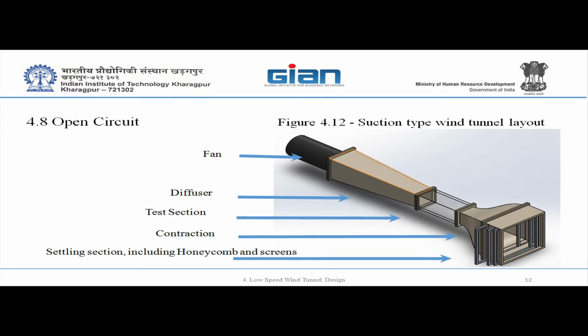To settle the turbulences, there should be some space. The settling of air is being done in the settling chamber by the elements that we are inserting there. You see the drawers we put there, starting with a honeycomb, and we'll talk about it in detail later on. And then you have meshes, screens, one by one, with decreasing porosity, starting with open and then closer ones downstream. This settles the noise in the settling chamber.